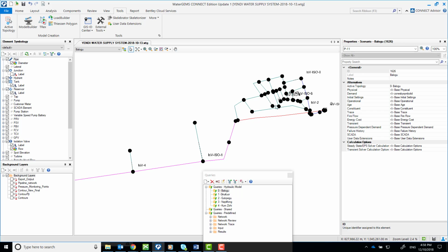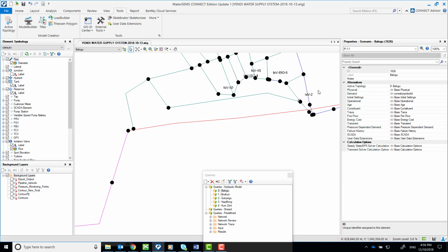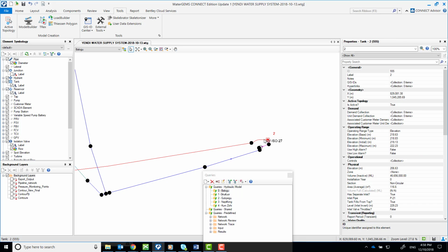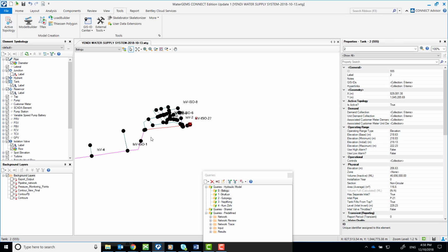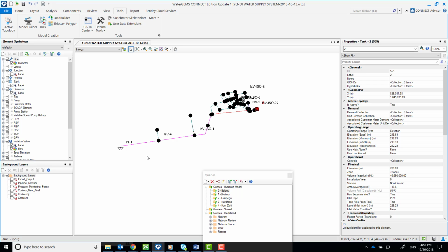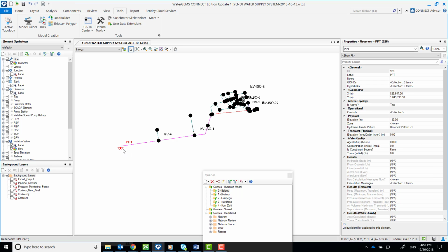networks. And what you want to make sure is that if this is a scenario that you have, you're only supplying water to Balogu, you want to make sure that you have read the water level at your tank. It seems like it's all gravity because there are no pumps here, so that will make your life actually easier. These reservoir levels, you want to make sure that they're okay. And wherever you have placed your nodes, your metering devices, that will let you know whether your demands for these nodes are matching your input from the reservoir.